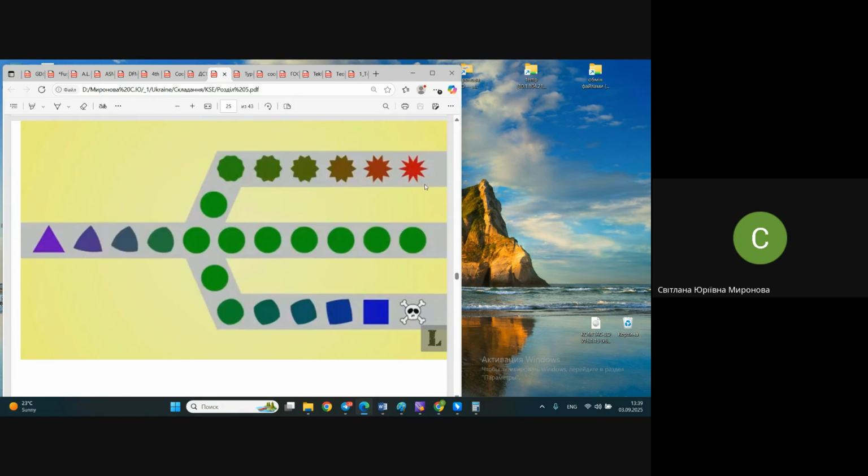During the studying, you already understand we practically do not use so-called direct metal forming. Shapes and sizes of objects may appear as a result of secondary forming. It means that we copy the sizes of tooling by our parts. So first we produce tooling, next on this tooling we produce some shapes and sizes, and finally they will meet in assembly jig, which is also produced from some pieces and with using of another tooling. That I hope you already do remember.